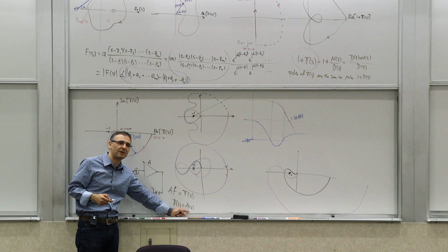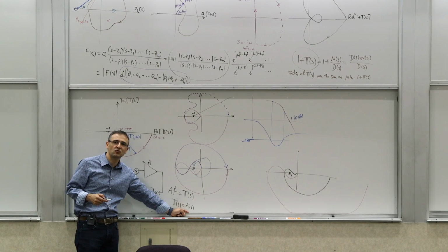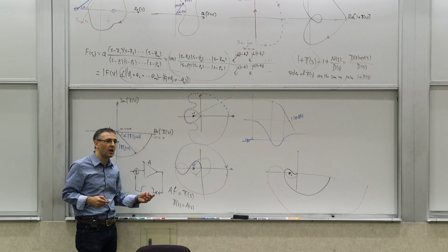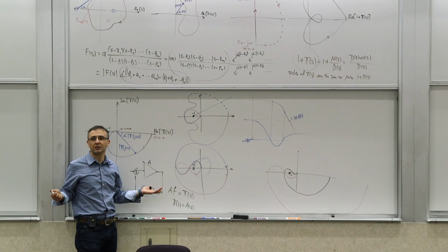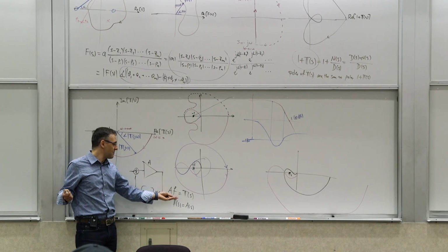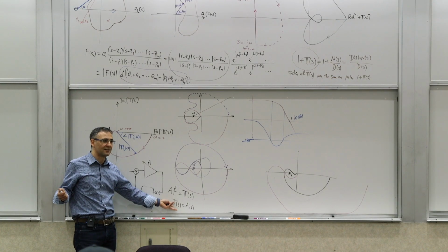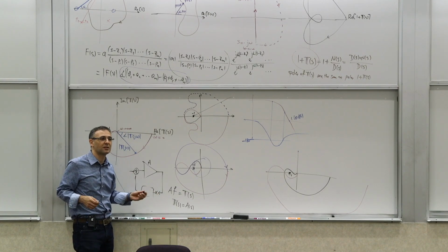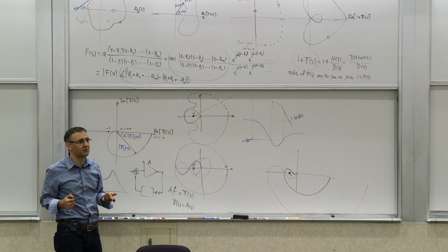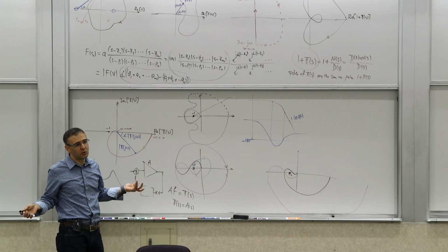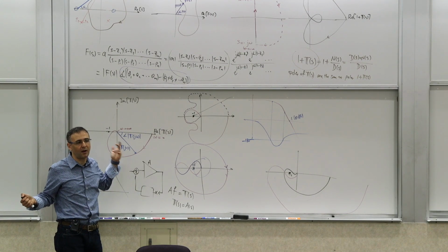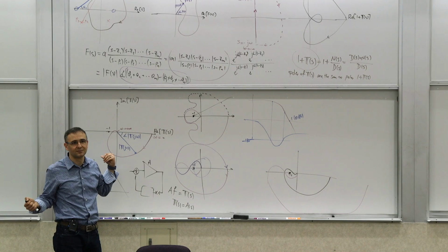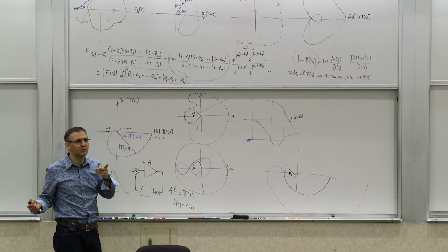But you have to realize that's a special case, assuming that you are going to go to unity feedback. A lot of times you may not want to go to unity feedback. You may go to actually less than unity feedback, and then you may be over-designing. Because you may try to stabilize something that's stable for unity feedback, but if you have no intention of ever using it in unity feedback, or you know exactly how you're going to be using it, you can do that, but it's an overkill. You're compromising something else somewhere else to achieve that. So that's a good question. Yes, very good. There was another question?